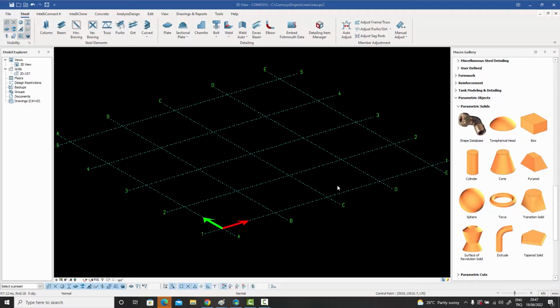So if you have an object which you're not going to change, which you're not going to detail in some way, you're just basically picking it off the shelf with a well-defined shape, it's a very good idea to use your shape database. And then another advantage is that you can create complex shapes, theoretically as complex as you want, and define them by using the primitives which we will talk about. So any shape of any arbitrary complexity can be modeled in the shape database.